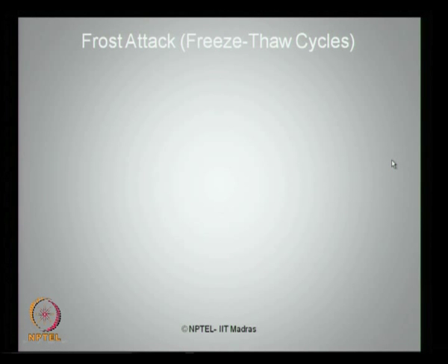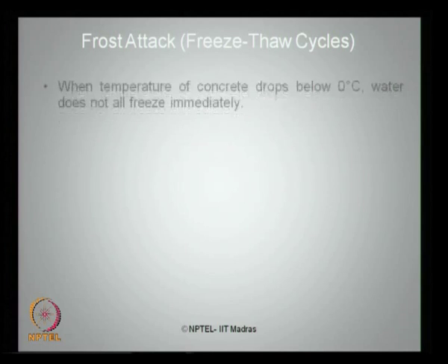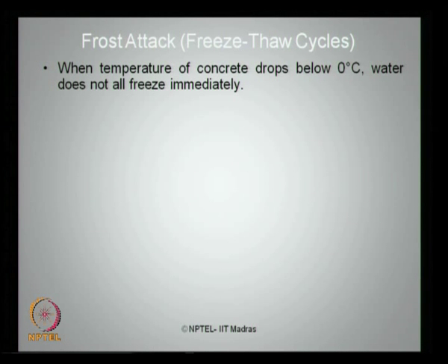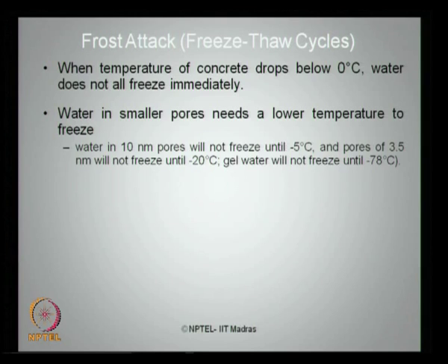As you understand, sometimes ocean structures are also subjected to reversal in terms of temperature, like freeze thaw cycles, what we call as frost attack in literature. When the temperature of concrete drops below 0 degrees, water actually does not freeze immediately. Water in smaller pores needs a lower temperature below 0 to get frozen.